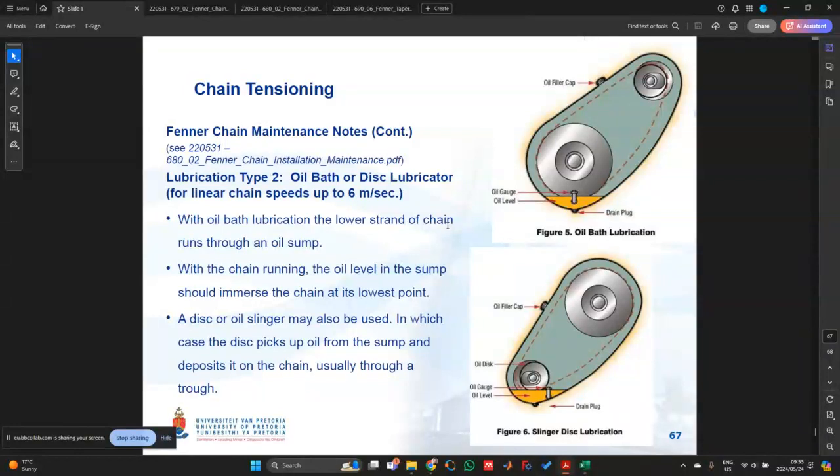So it's important that you remember that if you have that odd number, then you round up to an even number. The original mistake that I made over there was to say that if you have an odd number of sprocket teeth on your driver, then you need an even number of sprocket teeth on your driven sprocket, which is not correct. The actual number of teeth will depend on the speed ratio that you have available.